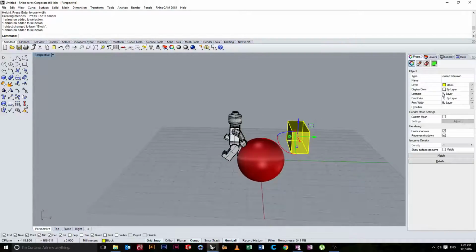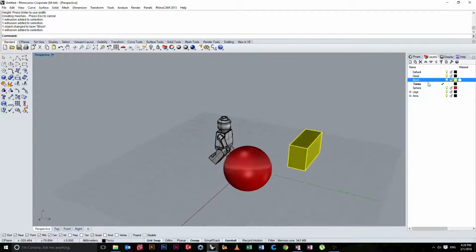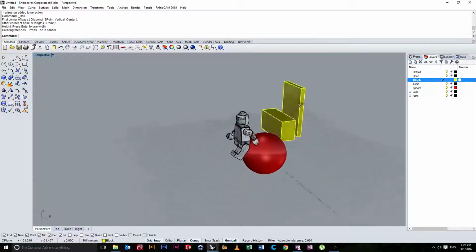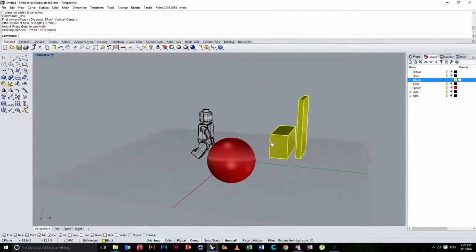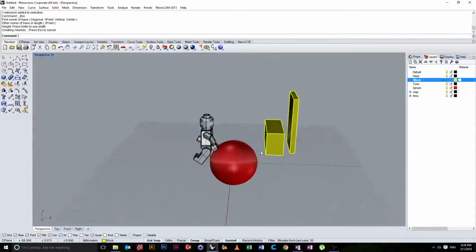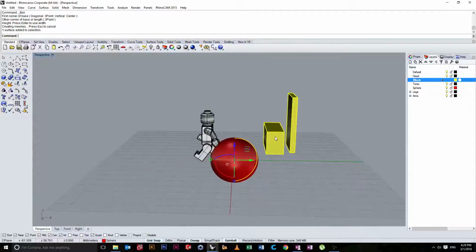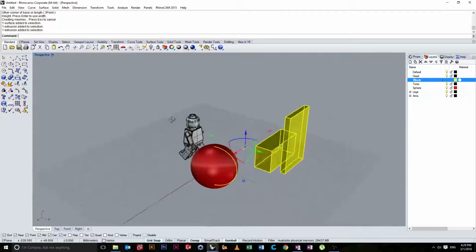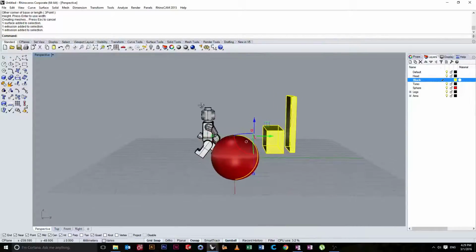You'll see here in the properties menu we have a layer, it's yellow, and we said the display color is set by layer. Alternatively, you can just change that manually, but by layer is a good default, and what that means is anytime we have that layer selected, so little tick, double click, you select that layer, anything we build now will be yellow. Again, it's a good way just to know what you're working on visually. Other than that, it doesn't have any other purpose.